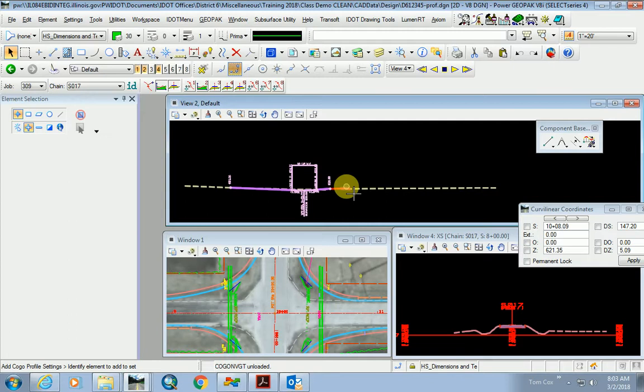And then you're probably going to end up tweaking the design speed a little bit if your intent is to match the existing super elevation on the curve. But then, even when you do that, it's always going to calculate your super elevation transition lengths and allow you to cut a cross section anywhere within that transition, and it'll know exactly what the cross slope is at that location based on shapes. So that's what we're doing now.